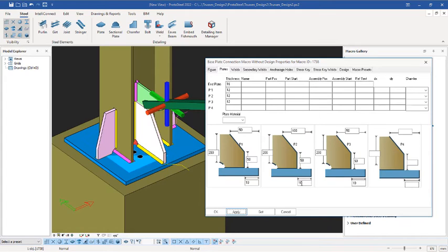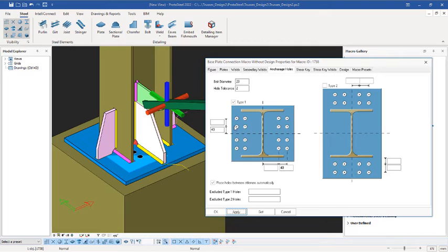Okay, so here the distance from the edge of the plate to the edge of the stiffener is 10 millimeters. Alright, so these are the necessary settings I did. The next setting that I want to explain to us is the anchor holes. If you click here, you have the anchor holes just like this. If you check in this, you see you have 2 anchor holes here and 2 on the other side, so we have 4 here and 4 there to add up to 8 anchor holes.